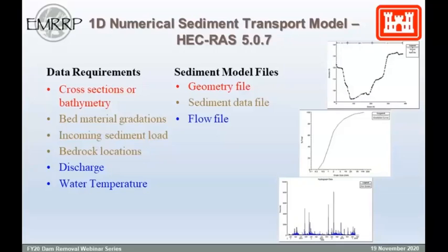But having that data can help you make certain decisions to have your sediment data file set up. You also need your discharge. You need some sort of a hydrograph that you're going to use for your study, and you also need water temperature to complete your flow file.